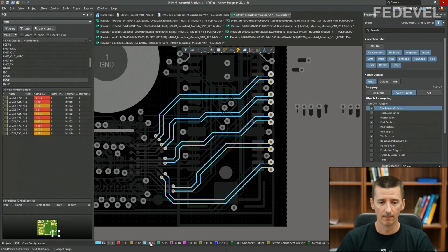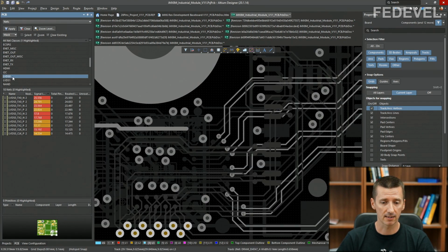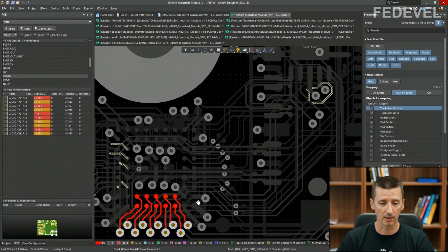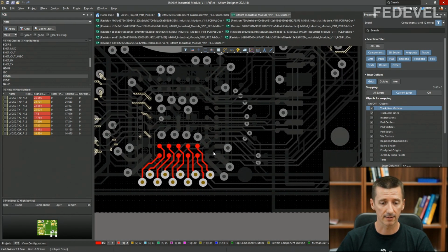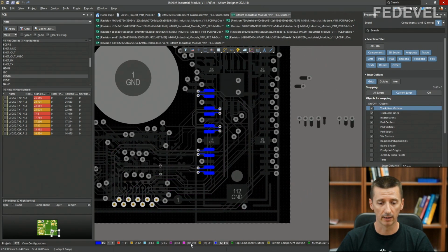That's how changing the pinout on the connector improves the layout. Notice the space between these differential pairs, a lot of space. Okay, for the LVDS0, very similar. All the signals now go on layer 10 and then they go on the bottom layer.